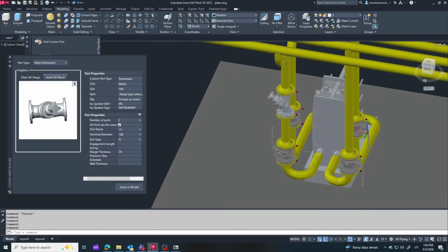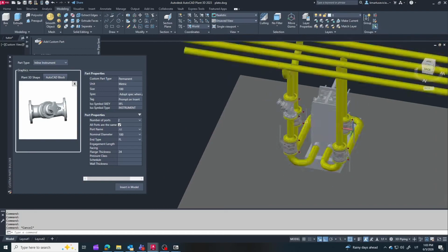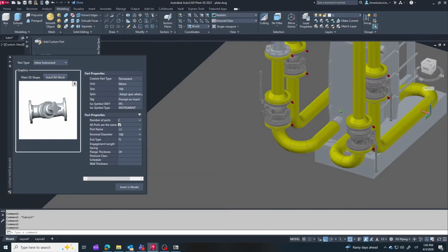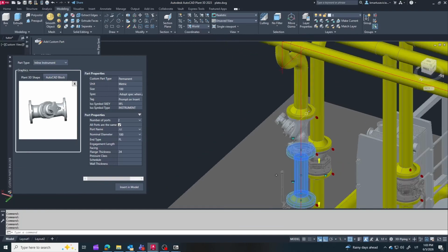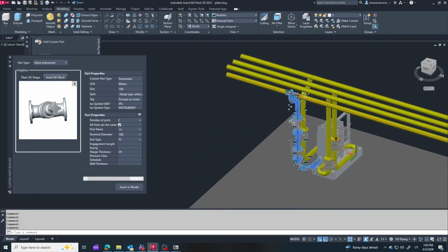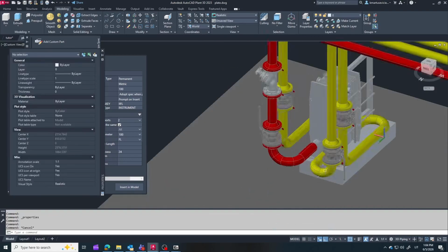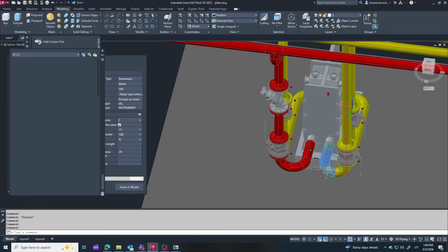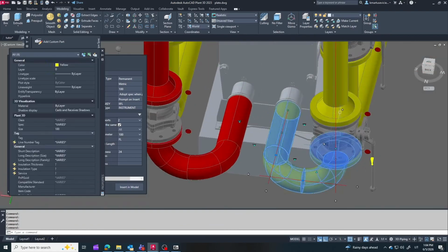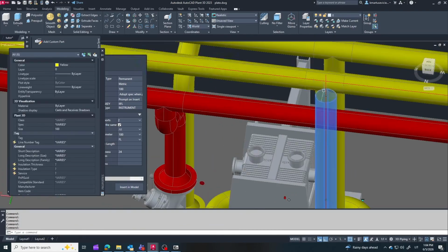Now that the piping layout is complete, let's set up the system color coding to make the flows instantly clear. On the front side of the plate heat exchanger, we have our cooling utility lines, blue for the cold water inlet and red for the hot water outlet. On the rear side, we connect the process lines for the product we need to cool down, which I've color-coded in green and yellow. In 3D modeling, you must clearly reveal exactly where each coolant and product line connects.